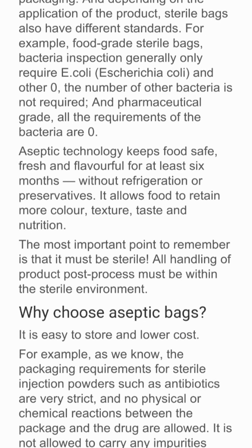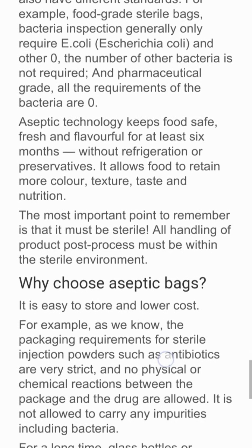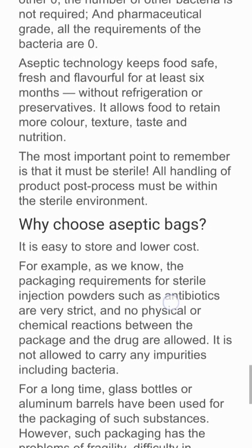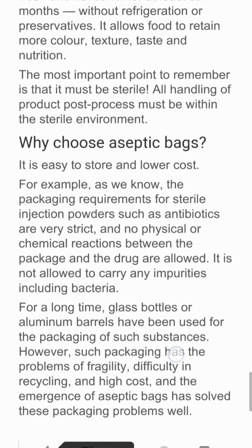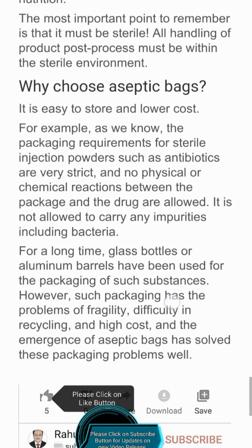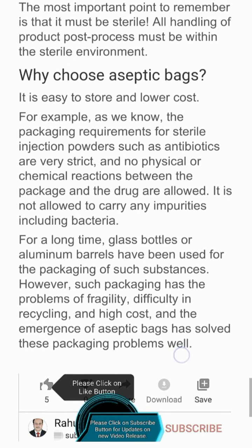For example, for food-grade sterile bags, bacteria inspection generally only requires E. coli, Escherichia coli, and other pathogens to be 0. The number of other bacteria is not required, and for pharmaceutical grade, the requirements of all the bacteria are 0. Aseptic technology keeps food safe, fresh and flavorful for at least 6 months, without refrigeration or preservatives. It allows food to retain more color, texture, taste and nutrition. The most important point to remember is that it must be sterile. All handling of product post-process must be within the sterile environment.